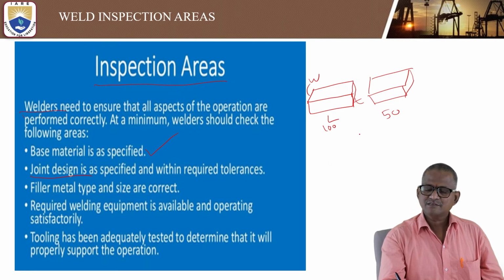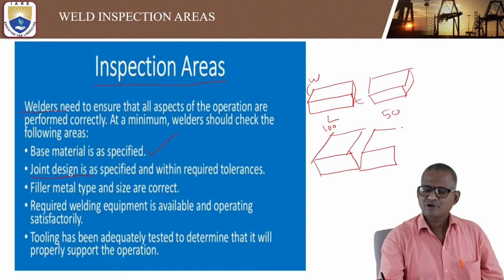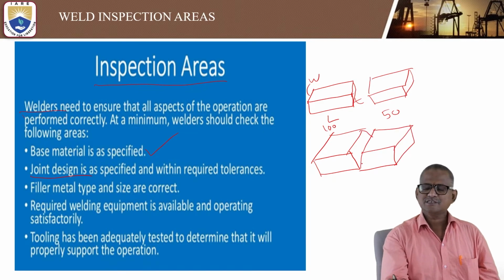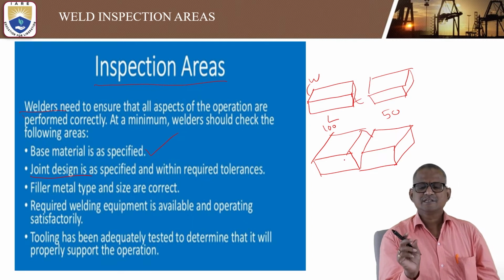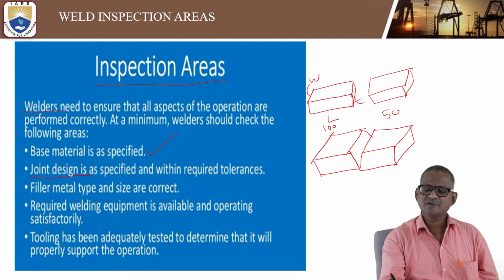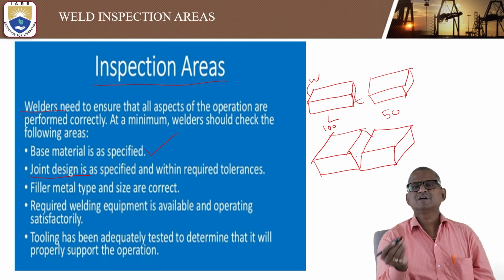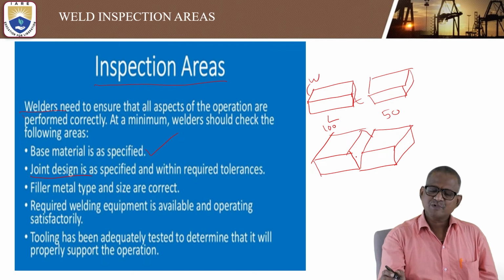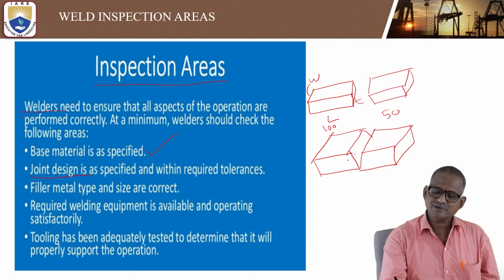In general, the component you perform welding on, first you prepare some V type groove. In that groove, how much distance between the two workpieces should be left, either 5 mm or 10 mm or 2 mm, based on the requirement only you can identify.